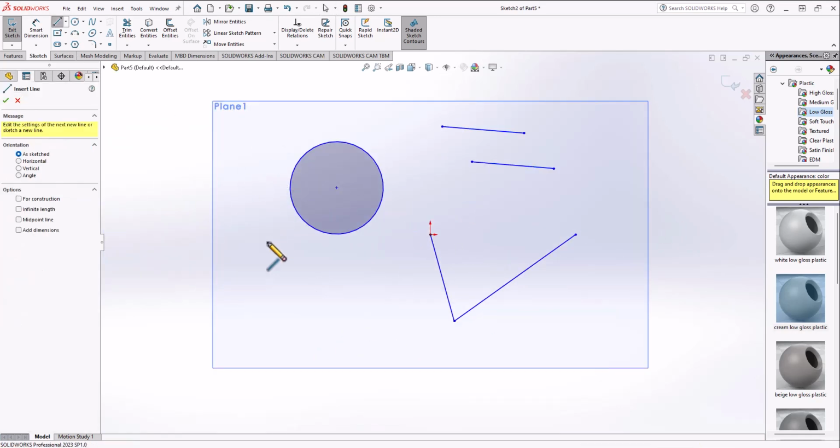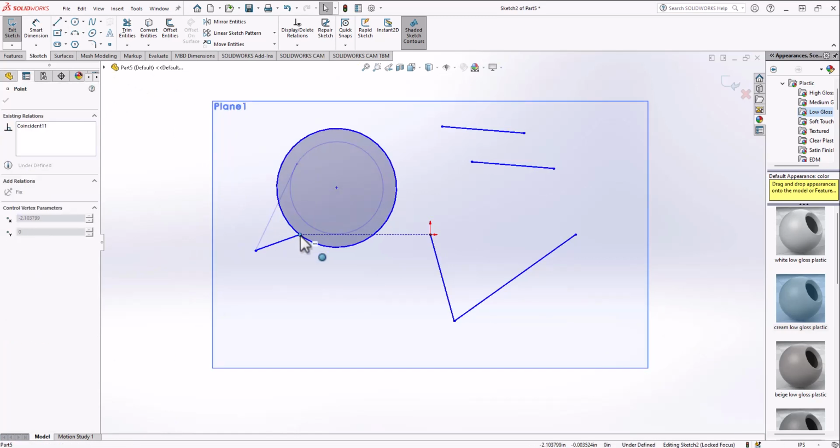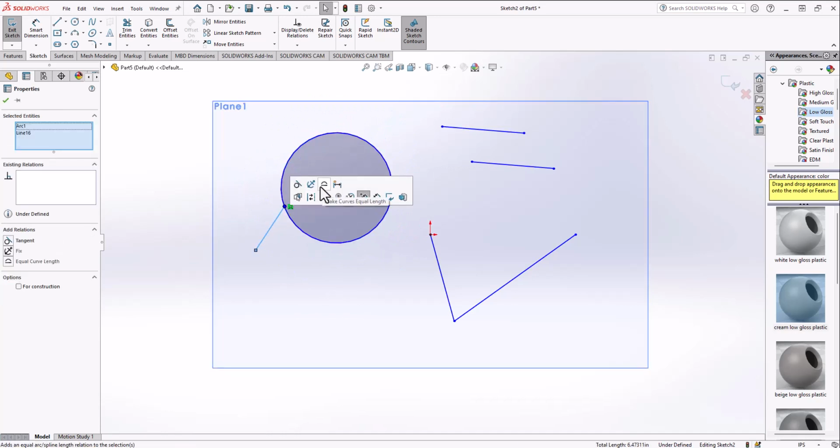The other constraint type would be something like, I've got this, and I use this a lot in tracks and stuff, but I've got this line going to the circle. So I can select these. I can have them have the same arc length. So that's similar to the equal sign, except in this case, it's using the perimeter of the circle, setting that equal to the length of that line.